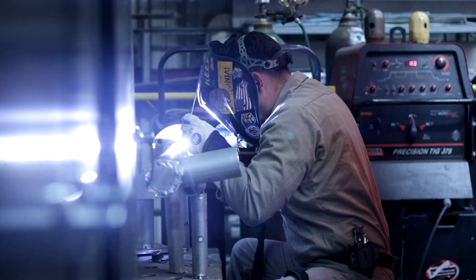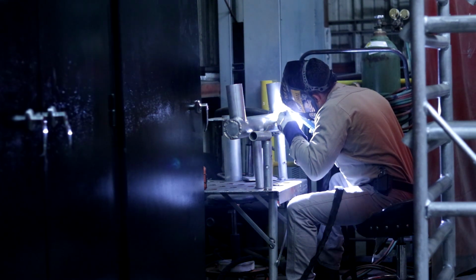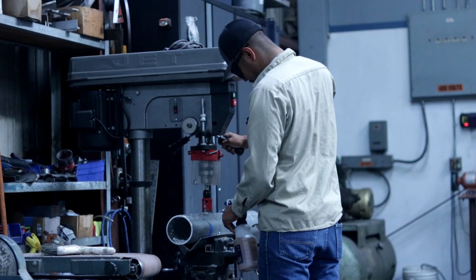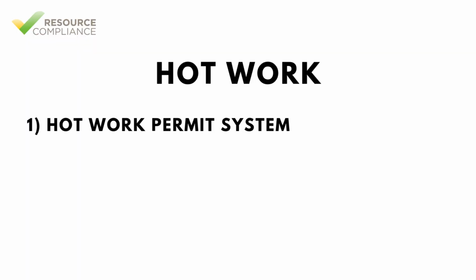In refrigeration plants, this includes welding, cutting, grinding, brazing, or soldering. Because these facilities contain flammable materials, refrigerants, oil residues, and insulation, hot work poses a significant fire and explosion hazard if not properly controlled. Safe work practices must be adhered to when performing hot work.